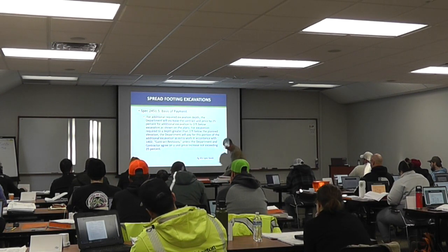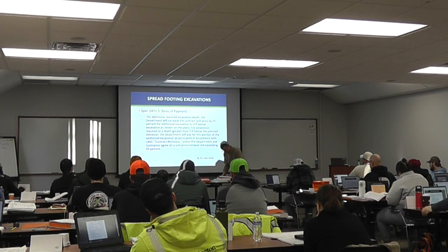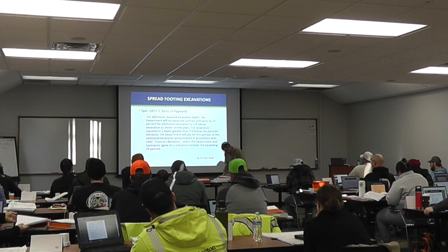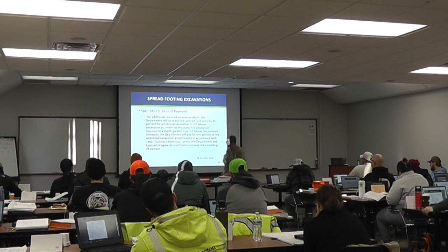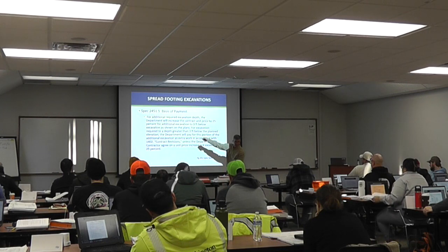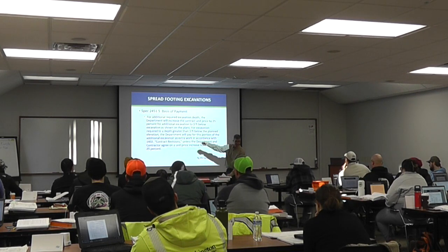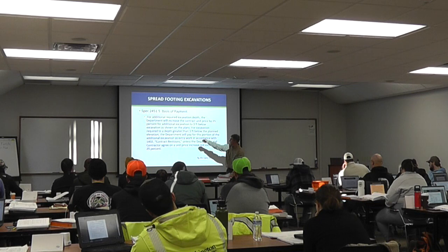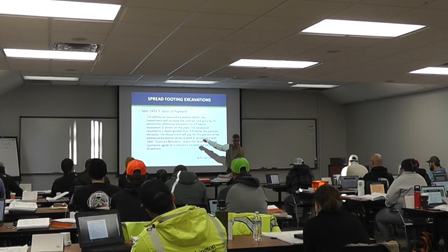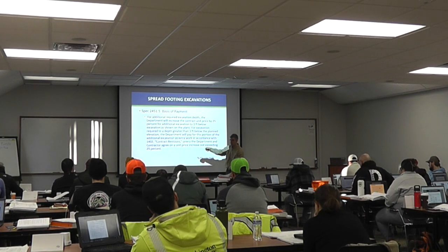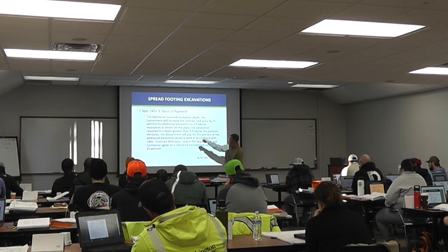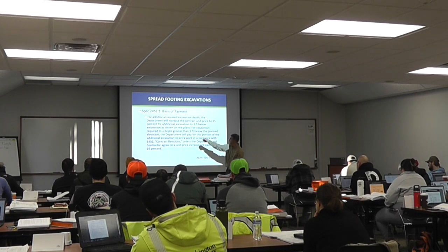And every single spec is going to be this way, where section 1 or 2451.1 is going to be a description of what's in that. 2451.2 is going to be materials. What are the materials that are referenced in that spec? 2451.3 will be construction, and what is the construction part of that spec? 2451.4 is going to be measurement kind of stuff, and then 0.5 is going to be payment.